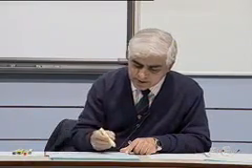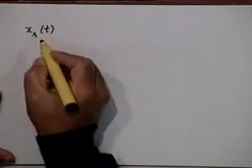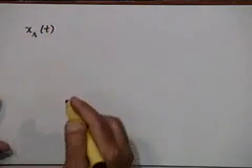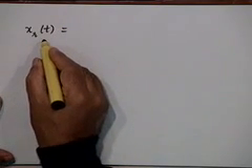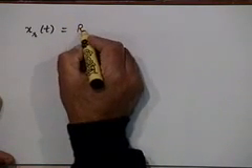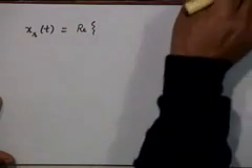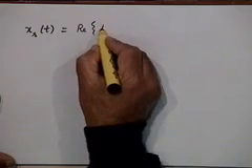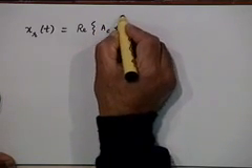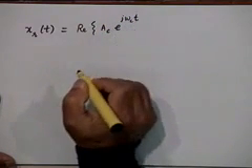Let's write this in the form of complex exponentials, because for phasor diagrams it is better to work with complex exponentials. So you can think of the received signal x sub r(t) as the real part of, now the first term was A_c cosine omega_c t, so it is the real part of A_c e^(j omega_c t), that is the carrier component.